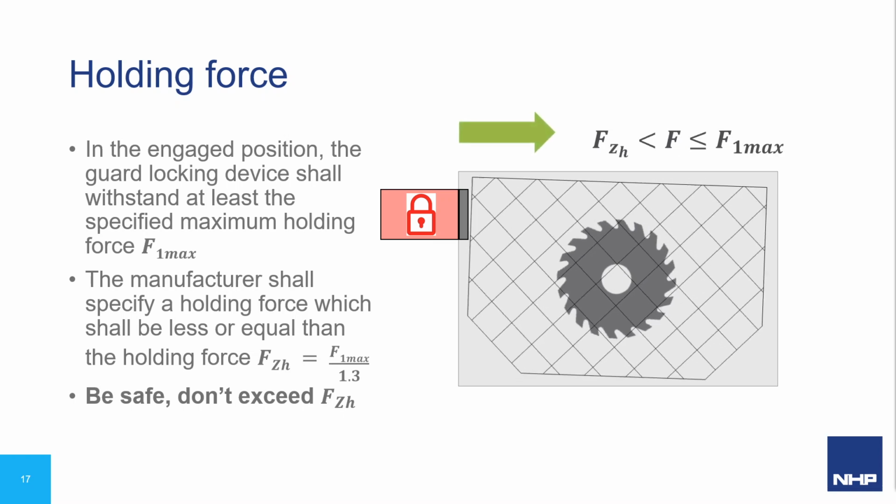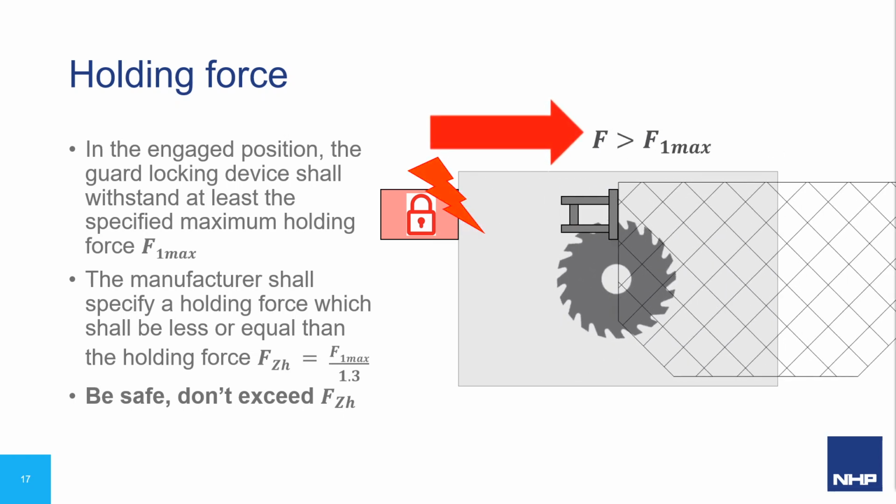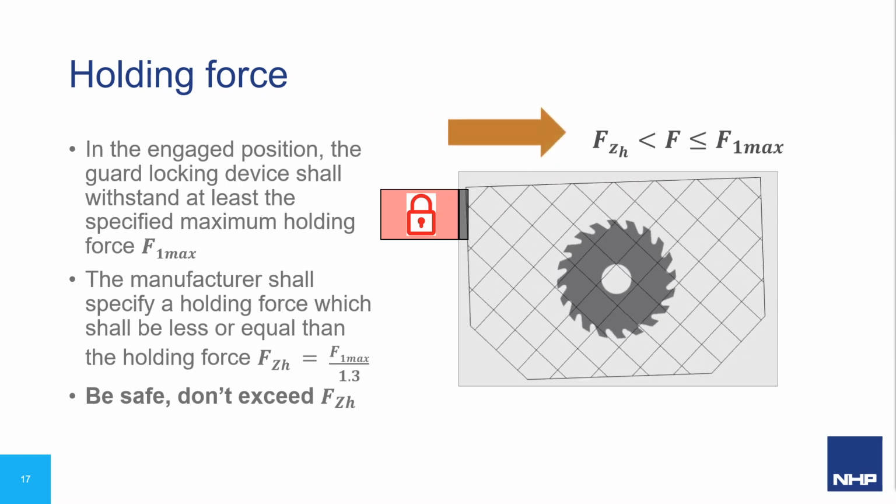You do not want to exceed the holding force. The result could be the guard being forced open and personnel exposed to hazardous motion. Guard locking devices are available in a variety of holding forces to make sure that you choose one that is right for the application.